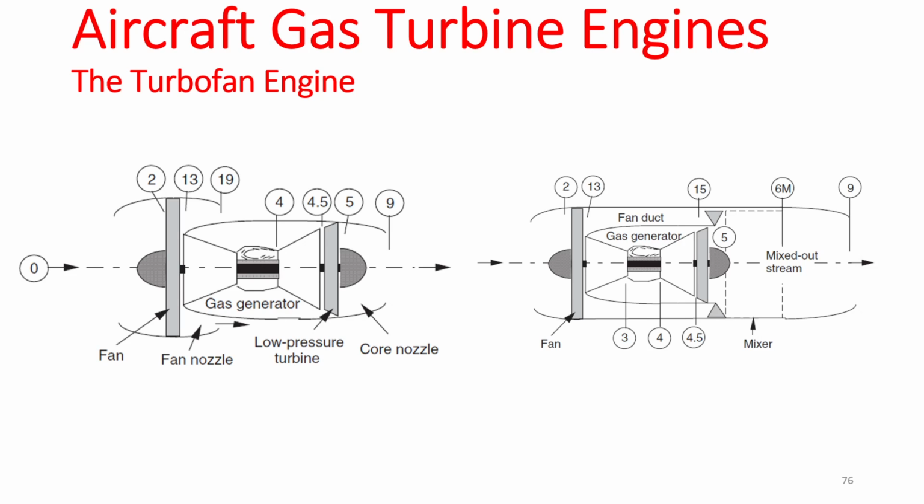Yes. So the second one is bypass, but yes. Mixes at station 6. Exactly. So this is going to be your bypass, right? And then mix here. Right? This is going to be your core, and whatever is coming into the core is going to be the core mass flow rate, right? Whatever is going around the core is going to be your fan mass flow rates.